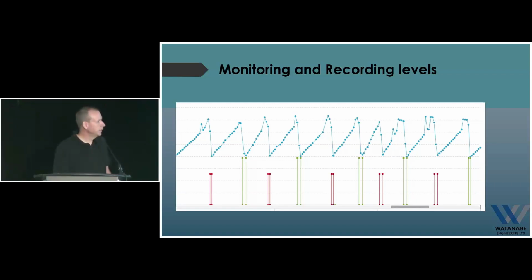The other thing this is going to tell us, of course, is that engineers love data. One of the things they're going to look at, particularly on water systems, but also on sewer systems, is, hey, you need an upgrade, but how much flow have you got? What are your peak demands? What time of day is your peak demand? Do you have any I&I issues? All of this information, if you're trending it, you pass over to the engineers. They work some magic, and then they can figure out what you need for pump upgrades and changes in your system to make things better.